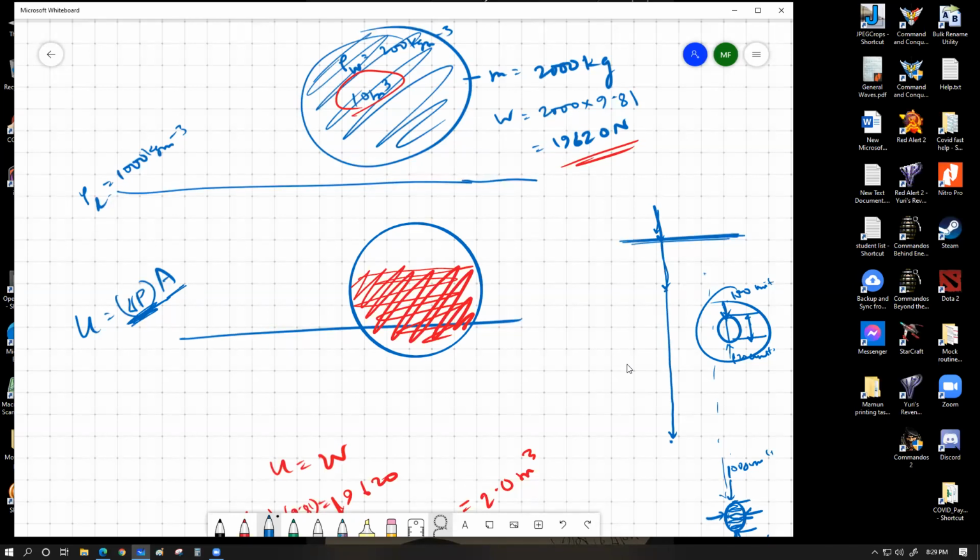The idea is very simple. If we want to keep something at a fixed position in a water body, we have to make sure of two things. First of all, the upthrust is perfectly balanced by the downward weight. Secondly, when this is achieved, the velocity should be zero as well. So you need to have some mechanism to control the velocity. You also need to have some sort of mechanism to control the forces.